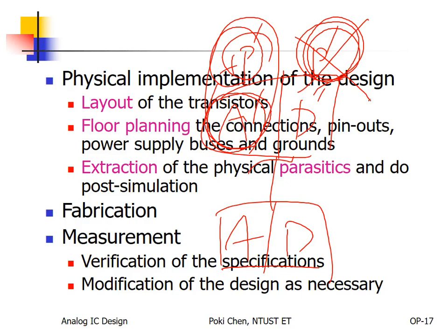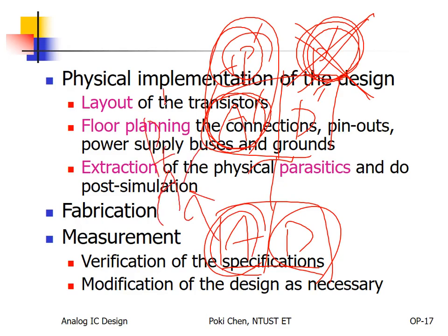So how to speed it up? Forget about this. Bingo. Exactly. Maybe you will be curious, how can I do that? You can separate your circuit into two parts, analog and digital. For analog, after layout, use the equivalent circuit and the parasitics. And how about the digital part? You still use the circuit from your pre-simulation. Good enough. In this way, you can speed up your simulation very much.